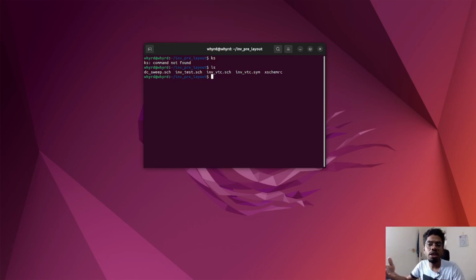Third, the easiest one, is to reduce the load capacitance, because if you design any inverter or any circuit, it will connect to the next block, and the next block is effectively a capacitance only. If you reduce the load capacitance, then your charging and discharging time will reduce, which implies faster operation of your design. So in today's experiment, we will mostly prove those things.